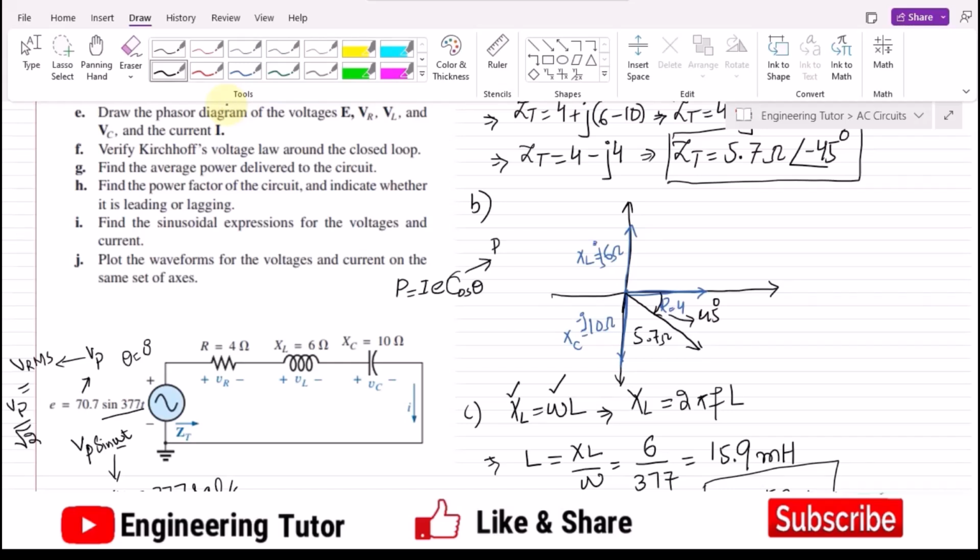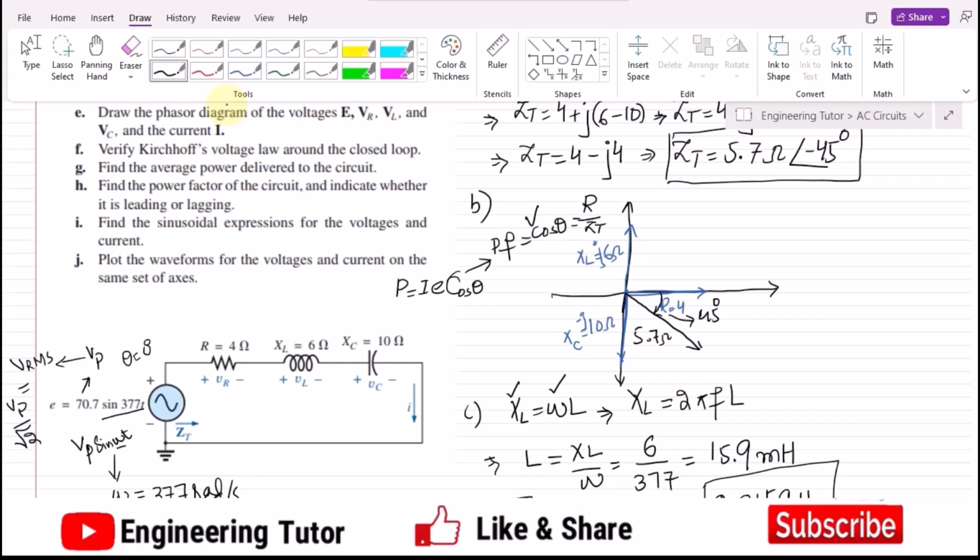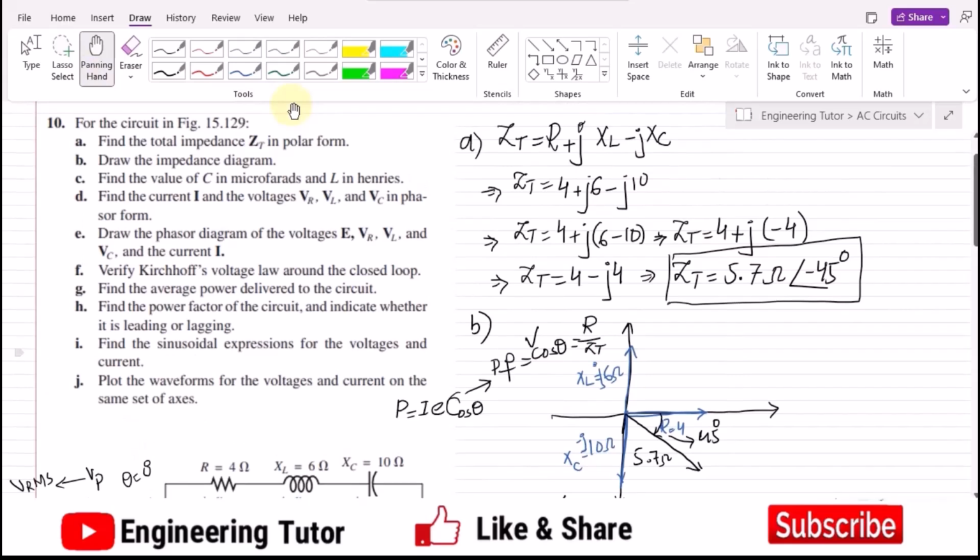This cos of theta is the power factor, which is cos of theta, or we can also do it by using R by Z of t. We have done it previously. Similarly, in part D, find the power factor of the circuit. By finding the average power, we also have to calculate the value of the average power and indicate whether it is leading or lagging. Okay, so that is a very important thing which we have to see here.